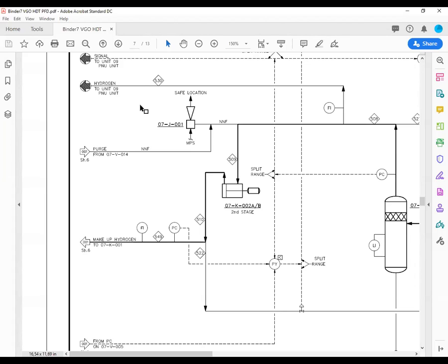My question is, is there any possibility to make a regeneration for the reactor, for the catalyst? And what kind of temporary and permanent poisoning is there for that catalyst? Yes, they always talk about the possibility of making regeneration in situ, but they don't recommend it because it is a very delicate procedure that can involve very high temperatures.